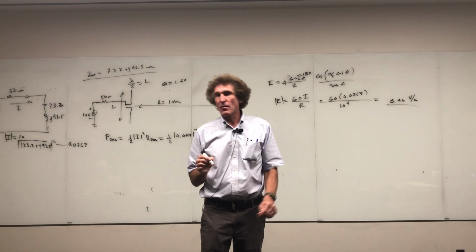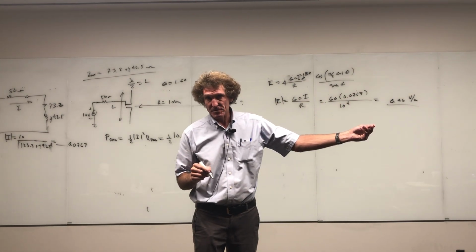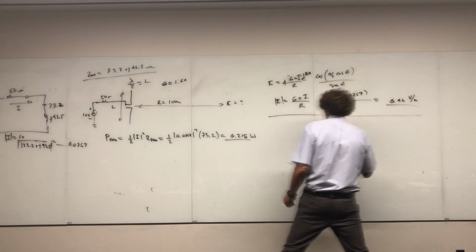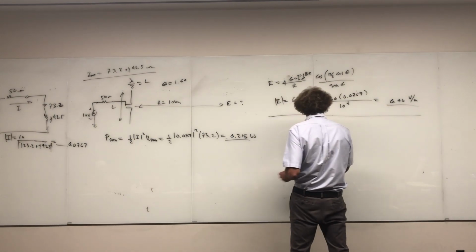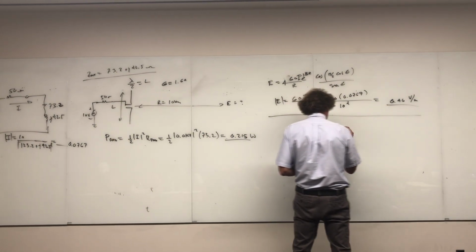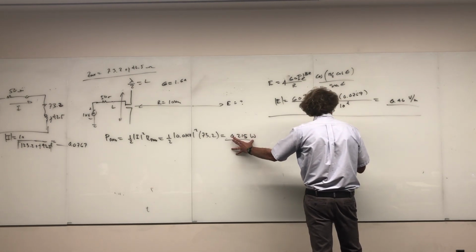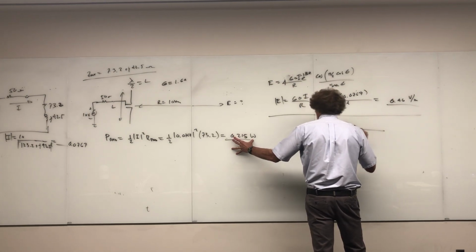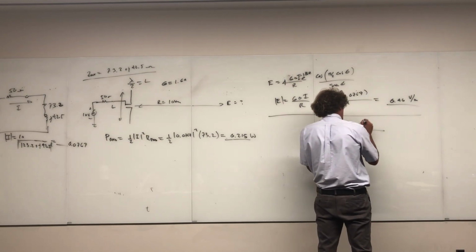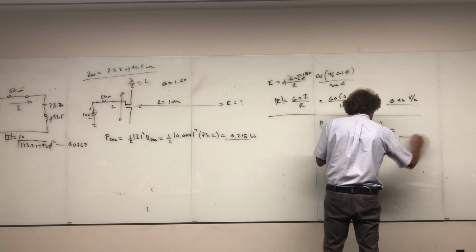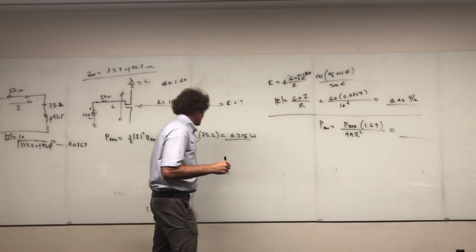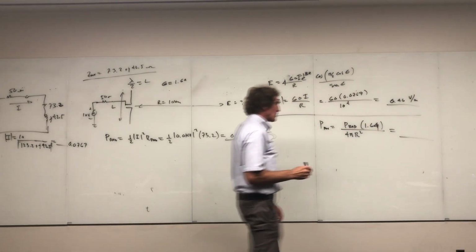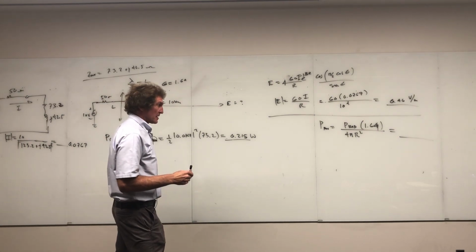Now we're going to find the amount of power at the point where we want the electric field measurement. Follow me? So that power out there, I'll put it here. This is going to be an average power density, equal to the total radiated power, P rad, over 4 pi r squared, r is going to be 10 kilometers, times the gain, 1.64. Go ahead and give me that. So we've got the radiated power, we multiply it by 1.64, and then divide by 4 pi r squared, and r squared is 10 to the 8th.